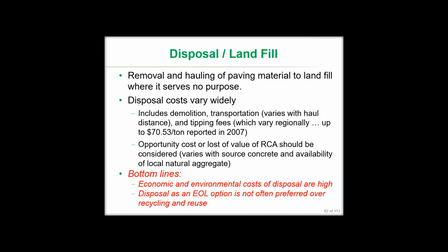There are obviously a number of costs associated with this: the demolition costs, hauling it off to the landfill site, transportation costs, and Hassan just talked about the costs of transportation on a cost or BTU per ton mile basis, and very similar sorts of things apply on the concrete side as well. And then the tipping fees, what the landfills actually charge for dropping the material there. Those vary quite widely around the country, particularly in the Northeast here where I live now. They're relatively expensive. They were reported as being almost $71 a ton, and that was 8 years ago.